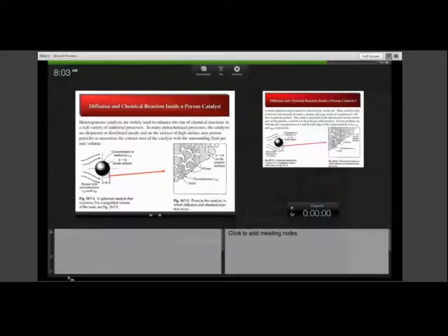Now, we've started with the simplest one-dimensional version of the constitutive law for flux, which has both diffusive and convective components. You remember the flux of A is minus C D_AB dx_A/dz plus x_A times (N_A plus N_B). This is the constitutive equation we've used throughout this set of notes, and we will continue to use that today,